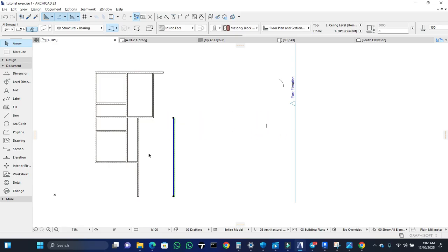Alright, so first of all, let's consider the back. The space for the veranda that we need is just 1.2 meters. So with the back wall selected, I use Ctrl Shift D, make a copy of it 1350 mm from the original point. I hold Shift, select the right wall, and click on intersect. So we have that, and I can now reduce this to this point.